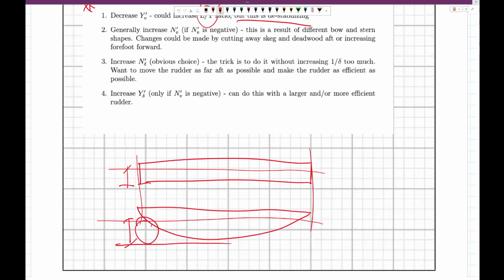Then you have this area here that water can just pass through quite simply. But in the top case, that's not possible. The water has to go around the backside of the canoe or underneath, and there's going to be a larger area of resistance. So in canoe lingo, we're increasing the rocker. This is known as the rocker. If you increase the rocker, you just make it more curvy, and you make it able to turn more simply.